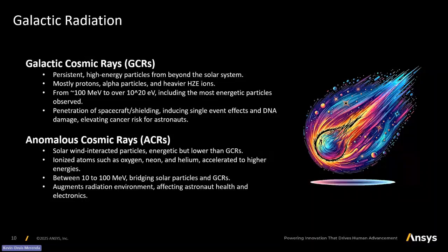And then some of the radiation is even more energetic, from cosmic rays, galactic cosmic rays, and anomalous cosmic rays that come from even outside the galaxy. These have very, very high energy and will leave charge behind and create an upset in your electronics. They're hard to shield. It's sometimes impossible because it would require too much weight. So being able to handle and understand these phenomena is important as well. The penetration through shielding is very high, very consequential in terms of health as well. And so being able to screen these cosmic rays is important.